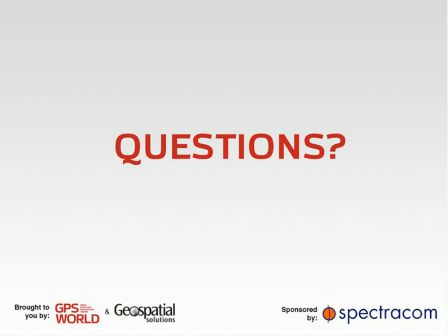Thank you, Julian. Since we have you live, Julian, would you like to address the second question, which had to do with simulating differential corrections signals? Yeah, certainly. The way we've done this in the past, because the LabSat is a live sky recorder, is we've actually recorded the augmentation signals at the same time. This can be in the form of the SBAS signals, so that's from the satellites, from things like the EGNOS and the WAAS system in the US. That's just on the satellite channel, so you get that kind of for free in the RF raw signal.